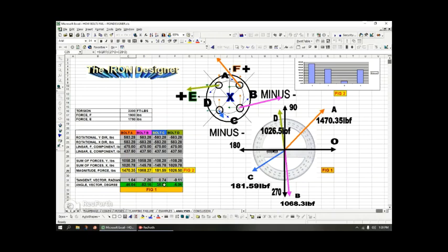You go to the left, you have another angle here of 36 degrees. You index the angle 36 degrees and you show your resultant force perpendicular to the angle according to the force diagram right here. So that's 36 degrees, and the magnitude is only 181 pounds. And that's simply because what we're doing here, this analysis, is just an instantaneous analysis.